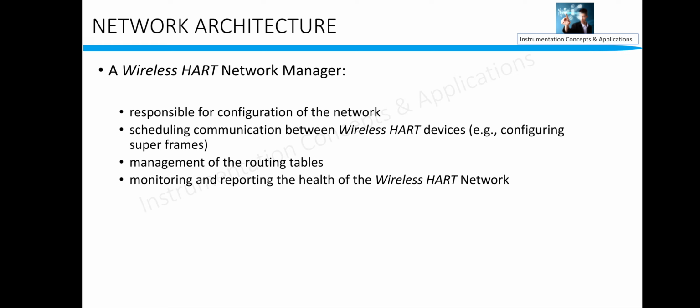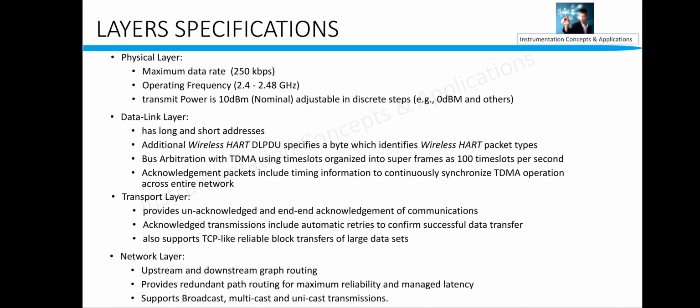Next, network architecture. I'm talking about this network manager, responsible for configuration of the network, scheduling communication between WirelessHART devices, management of the routing tables, monitoring and reporting the health of the WirelessHART network. This is the main use of the network manager actually.